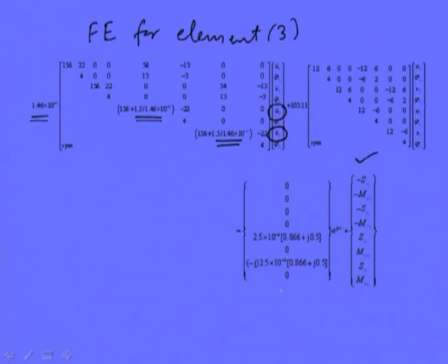External force is getting changed because now this represents the unbalanced mass, where omega is the spin speed of the shaft, and this particular quantity is e to the power j theta.